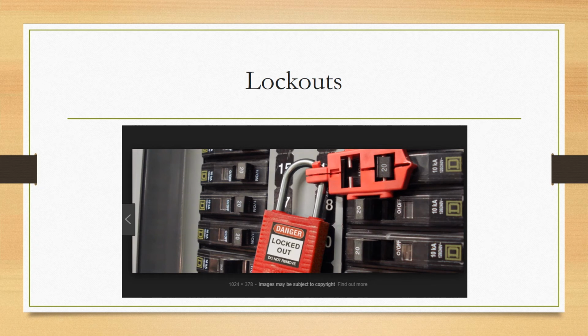In this phase we put lockouts at various places, like the control boards of various machines such as sewing machines, grinding machines, punching presses and milling machines, because then an unauthorized person cannot change the calibration, and if anything happens such as unlocking and maintenance, only an authorized person can change the configuration of the machine, such as calibration, resetting, etc. From our investigation, we found that employees were changing machine configuration by themselves, which was a major cause of defects.